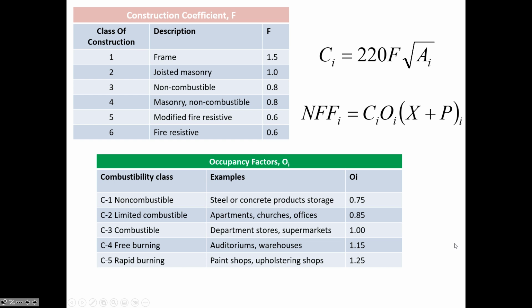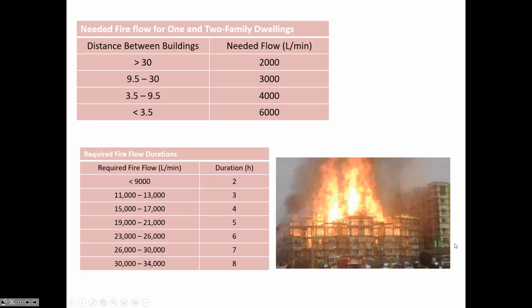So there's a possibility for really widespread variation in fire demands from one location to the next. And it's important just to be aware that you need to be really cautious in making assumptions for fire flows, and make sure that the people who are estimating the fire flows are licensed, and there is a fire protection licensure in the same way that there's licensure for civil engineering at the state level.